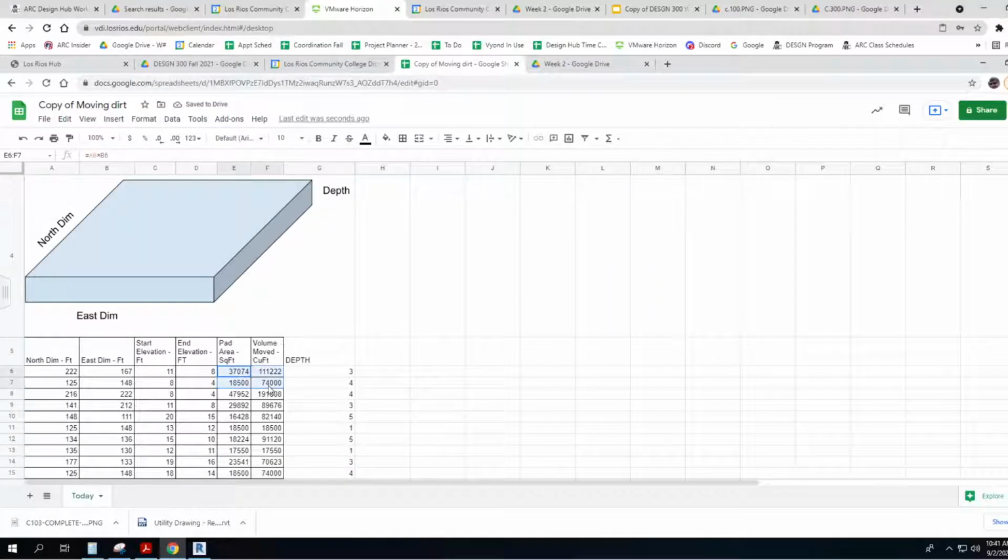And that's cool. So now I've got my set of calculations for the building pads. And if you ever work on a development where you're putting in 5 properties, 10 properties, 20 properties, this is just the first thing that you do. And then you start calculating allowed patios and minimum and maximum amount of planted area and minimum and maximum amount of shade.